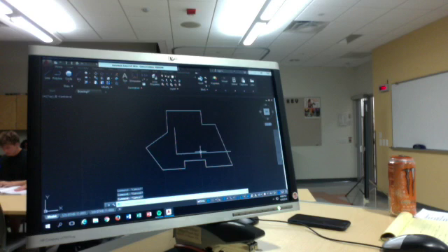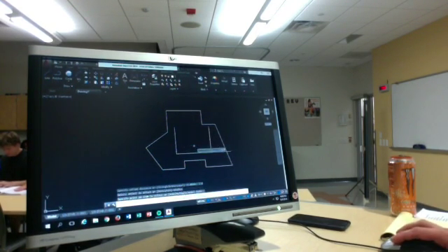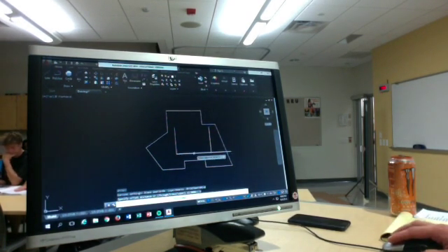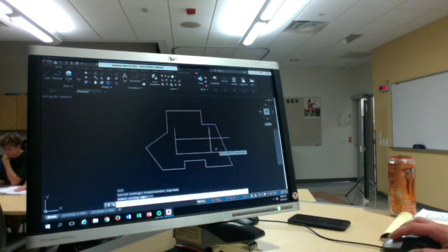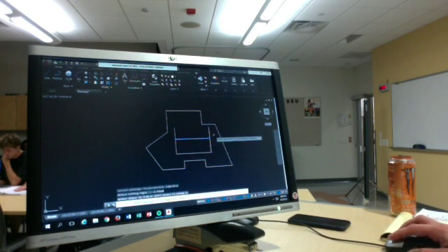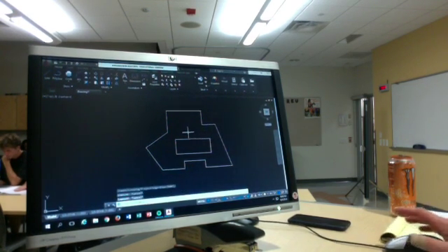We know that it is 2.5 wide, so I'm going to offset this line 2.5. And then, how tall is it? It's 1 unit tall, so we're going to offset up 1 unit. And then we can use this line to trim because it's outside of this line. So I choose that, trim those. Same thing right here. And we have the second one created.